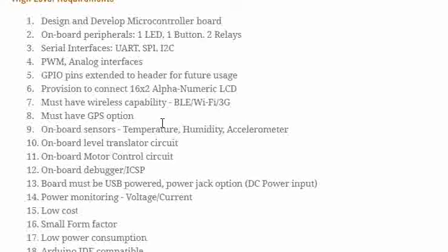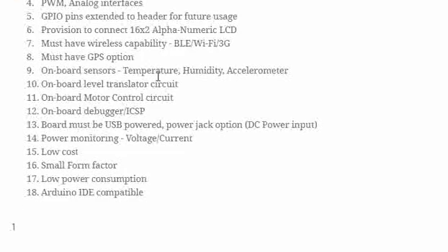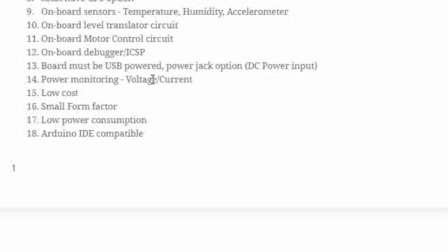and there is an option to have GPS as well. And it should have onboard sensors like temperature, humidity, accelerometer, and they're also asking for an onboard level translator circuit, and they are asking for an onboard motor control circuit. You should also have an onboard debugger/ICSP, and then the board must be USB powered. You can have a power jack option, but basically it's a DC input, and then power monitoring.